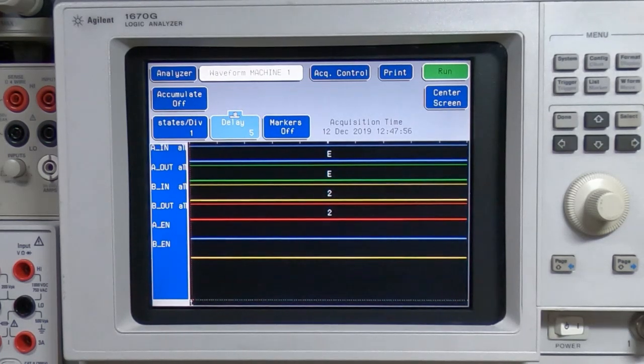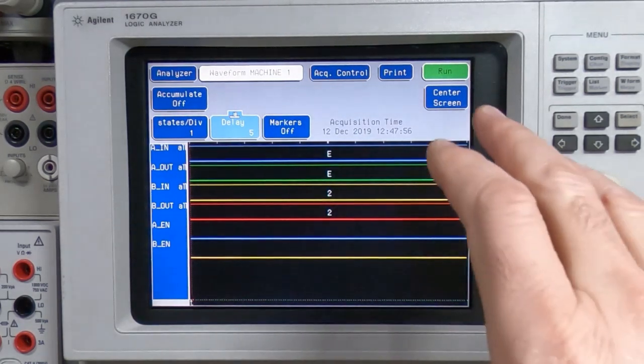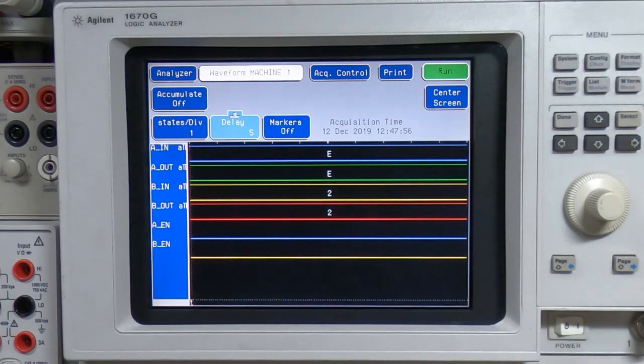It may seem to be slow and long-winded, but it does save a lot of time in the long run. I don't end up chasing myself in small circles trying to figure out why I've replaced a part that seemed to be faulty, and yet now it's still seeming to be faulty and the machine's still not working. It doesn't actually take as long as it may appear to set this up. Once you've got the configuration set on your analyzer, you can store those to hard disk, and it then just takes 1 or 2 minutes to test each type of device.